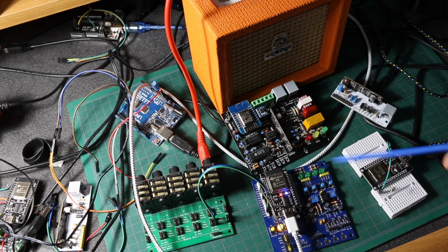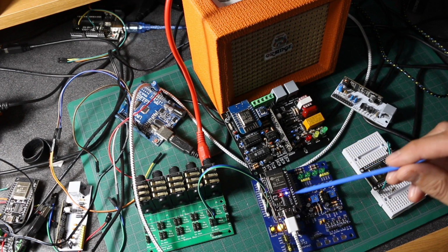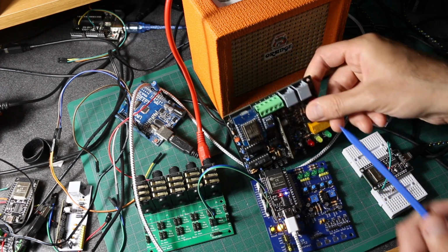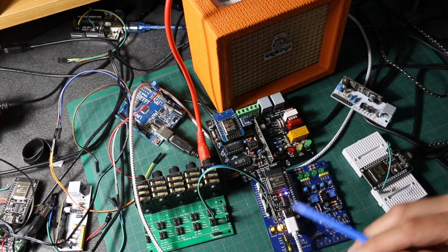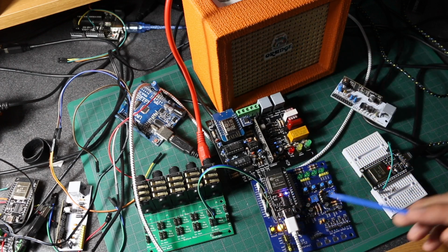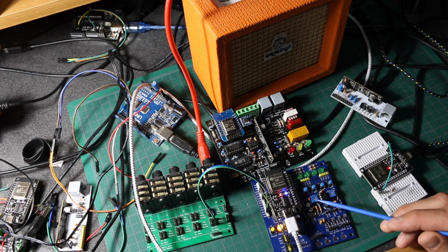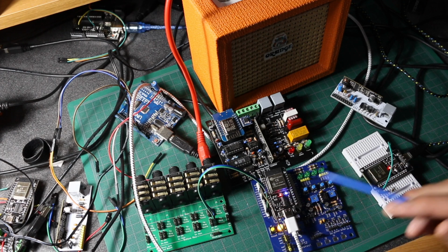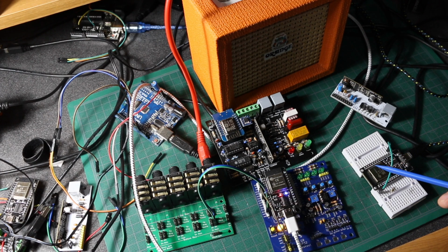What I wanted to do was strip down the features and start over just looking at Wi-Fi between these modules, because I want that to be a trunk line. Back on this board, I had RS-485 cables running between the two stations. I want to be able to just have one talk over ESP-NOW wirelessly to the other if it wants to place a call and find out, is this node busy or can it accept a call? And then it would make a phone line wire connection so the two phones can interact.